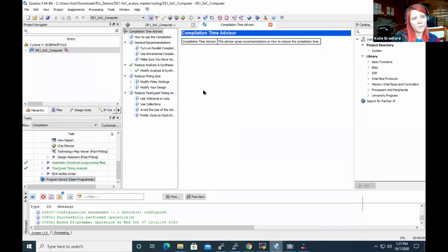What do you mean by at the cost of timing? What that means is that the F max, the maximum frequency at which you can run the system, goes down, because the compiler doesn't try as hard to squish everything together on the FPGA. I was just speaking for intermediate things as opposed to our final max nodes step.